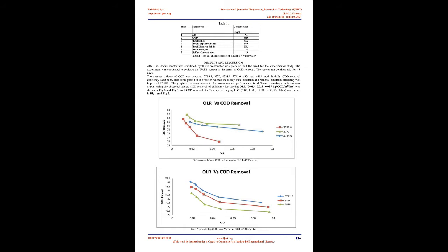Experimental setup: a bench scale continuous upflow anaerobic sludge blanket, UASB, reactor made of fiberglass was used in this study. The reactor had an internal diameter of 11.5 centimeters and a total height of 98 centimeters, resulting in a total volume of 10 liters and a working volume of 5.4 liters with a gas headspace of 1 liter. The reactor was fed with the substrate using a peristaltic pump, model PP30, Michelins.